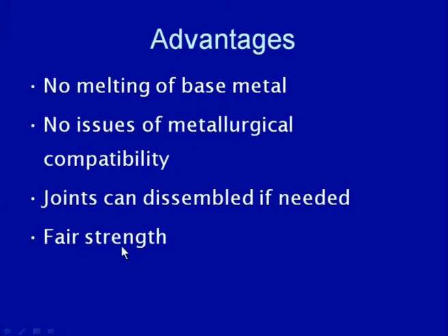The strength of the joint is also fair, but it is not as high as that of the typical weld joint. So, under conditions where very high mechanical performance is not expected from the component, braze welding can be very successfully used for development of the joint, the braze weld.